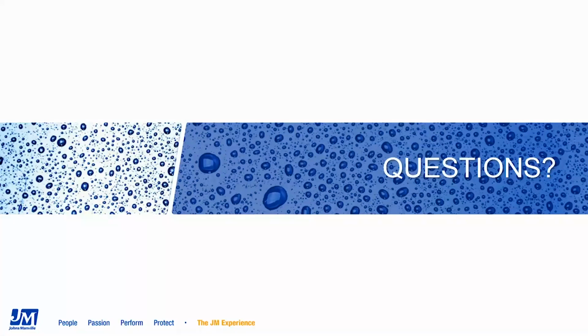Excellent, thank you. This next question, I'll offer it to both of you. Do you see insulation installed in cells, so that if a jacket or vapor retarder fails in one location, water doesn't spread as far? Matt, is that something you've seen in the field? I've seen that in the field in the past, industrially and in commercial applications too. The use of vapor dams in insulation systems could isolate and localize any kind of issues that you would have and keep them from spreading. Okay. Marybeth, do you have anything to add to that? No, I don't think so.